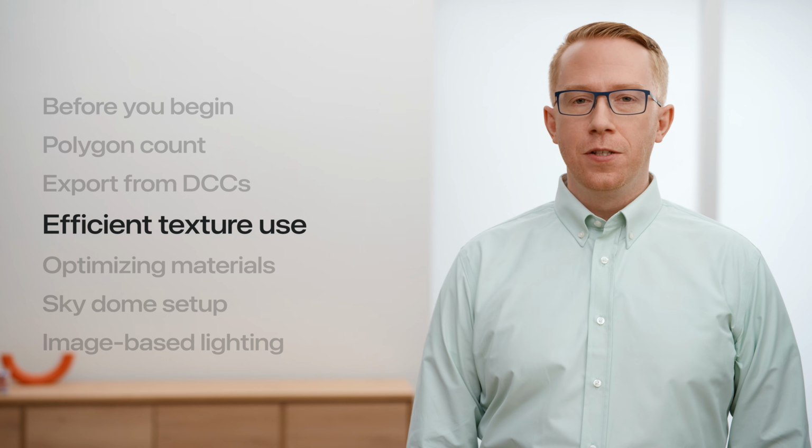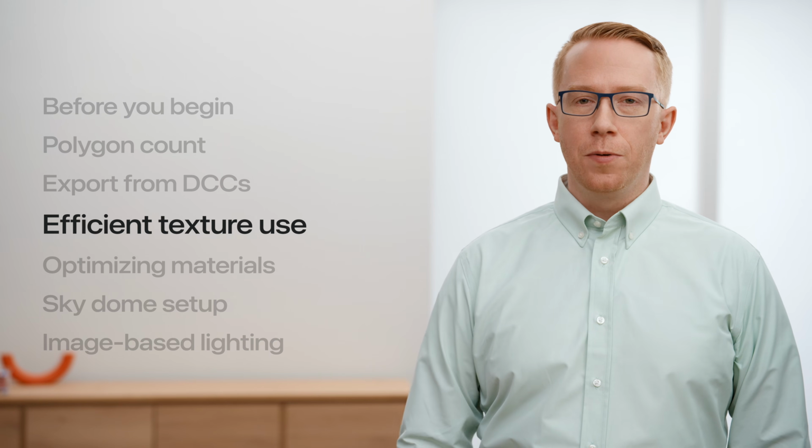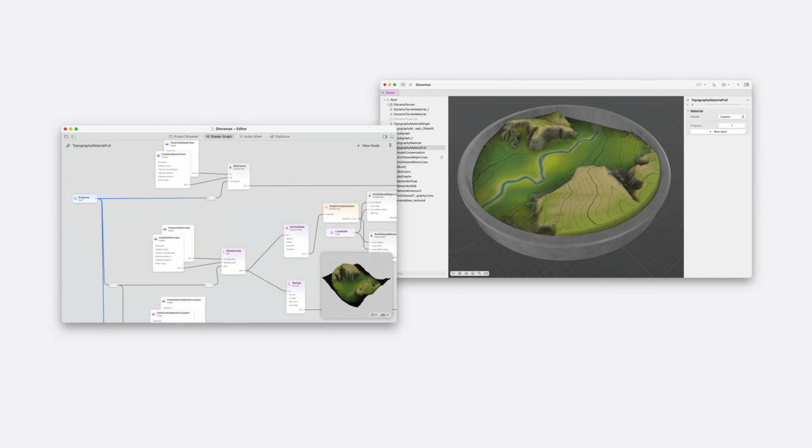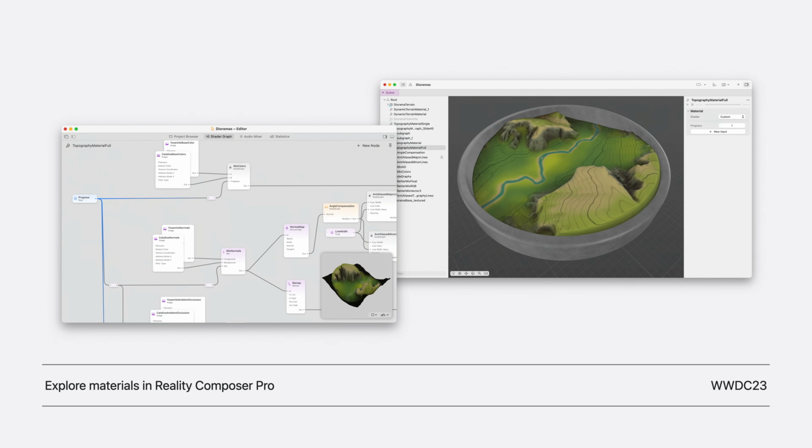Now, let's move on to applying our textures and see how we can make them more efficient. We'll use Reality Composer Pro's shader graph to set up our materials and textures. If you need a primer on setting up materials in shader graph, I highly recommend you check out Explore Materials in Reality Composer Pro, session from 2023. I've got a basic PBR material already started for this asset and applied. I just need to apply my textures.